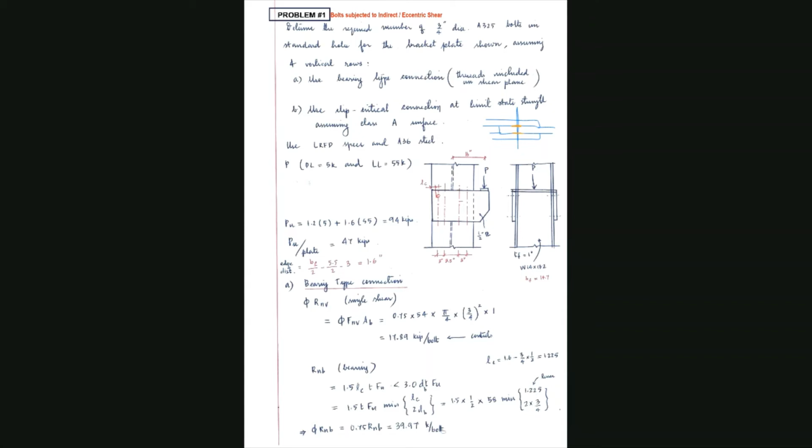Now this is the strength from bearing, and this is the strength from shear. Now which one is more critical? Shear. So this is your capacity in shear. So from here, the capacity of the bolt will be taken as this one, the least value.